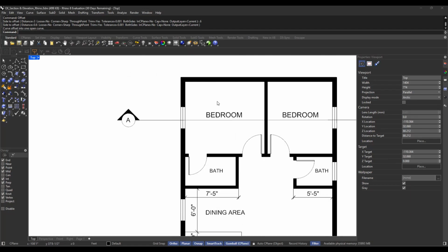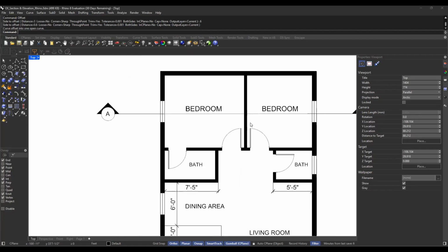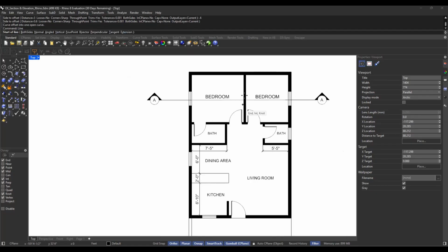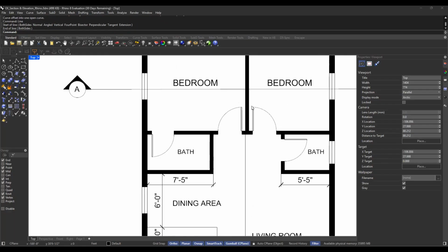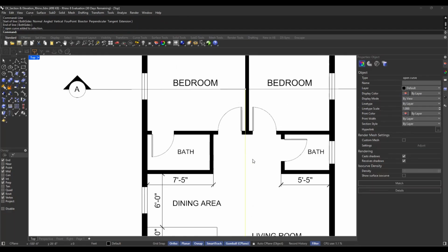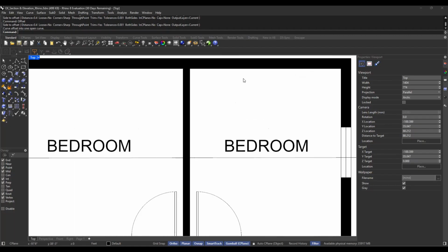After this, you remember we have this elevation or this face in the interior, and then we'll see, because the arrow section is upright, so I have an interior wall. So I'm gonna just draw one line from here to here, and then you can also offset this. You can say, okay, offset thickness was 4, here we go.